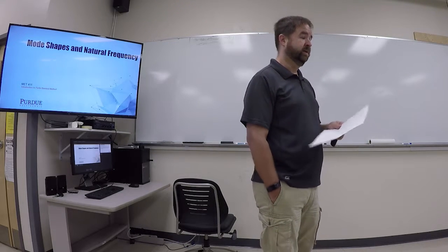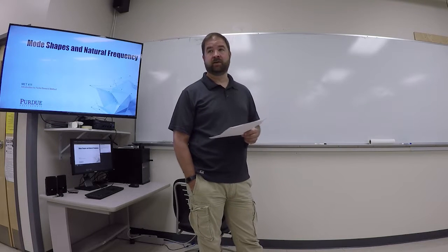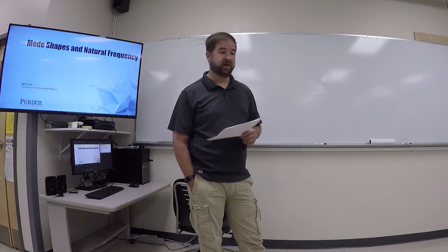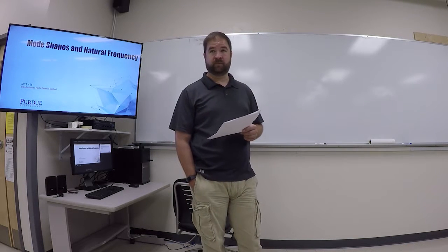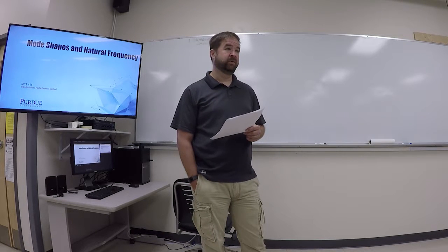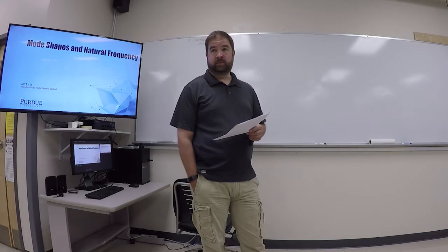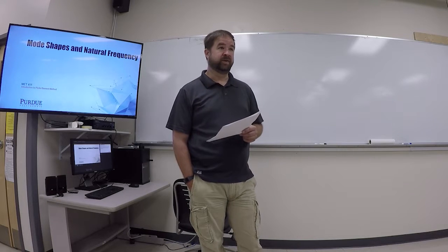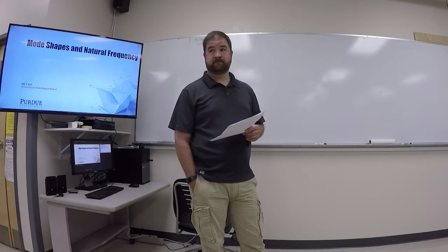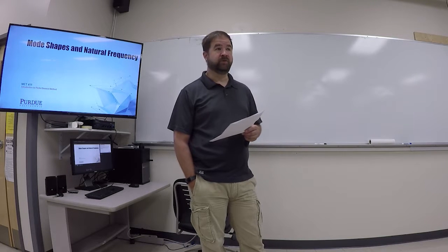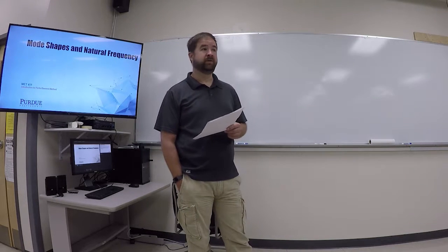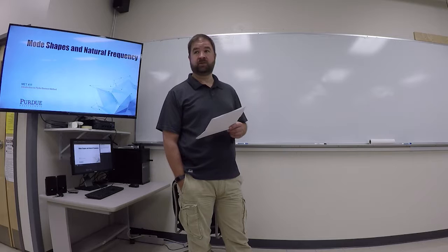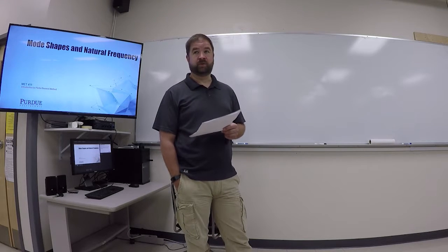One of the things that's a little bit different, I'm maybe jumping into talking about the analysis a little early, but since I brought it up, is that depending on how your model is constrained, you're going to get frequencies that are 0. And we don't care about that, because a natural frequency that is 0 means rigid body motion. If you have an unconstrained model, you will have rigid body motion, which means you'll have some natural frequencies of 0.